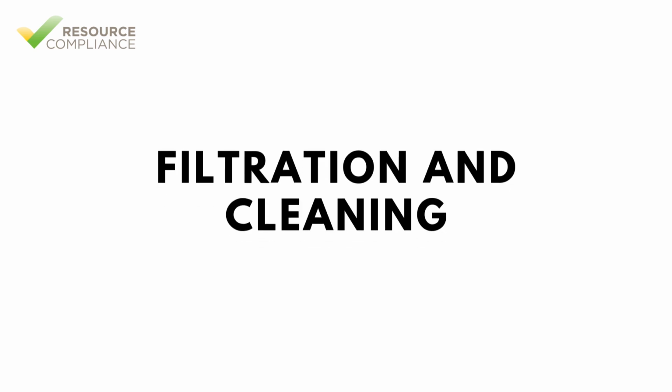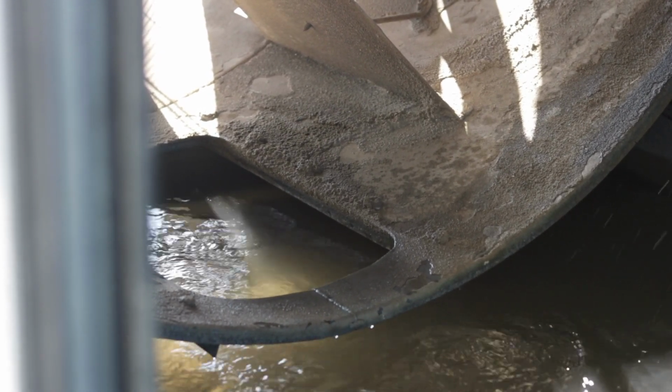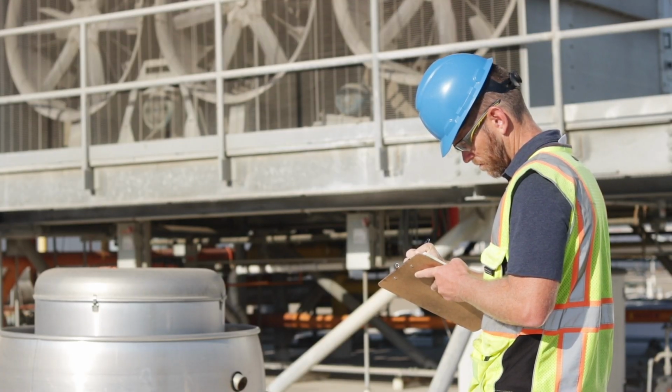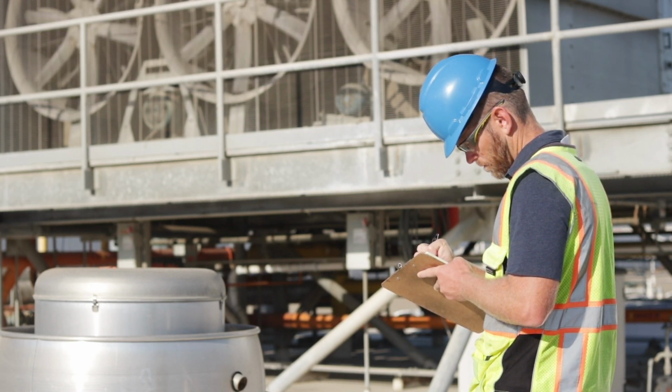Filtration is used to remove debris, dirt, and other suspended solids from the circulating water. Periodic cleaning is essential to remove accumulated biofilm, dirt, debris, and scale that forms on surfaces. Most facilities hire a qualified water treatment professional to oversee the water treatment program. However, every refrigeration professional must know how to monitor the program.